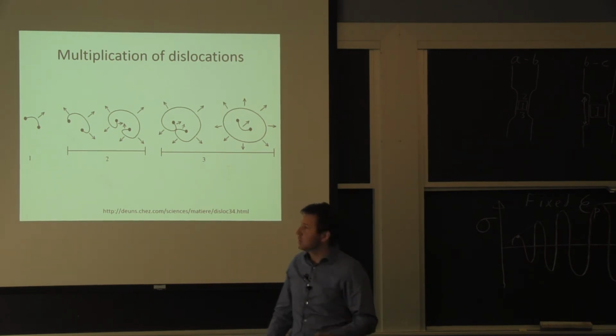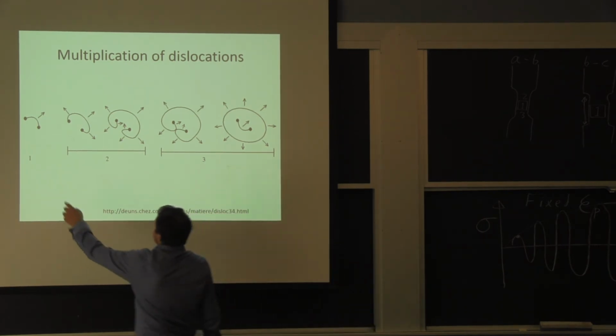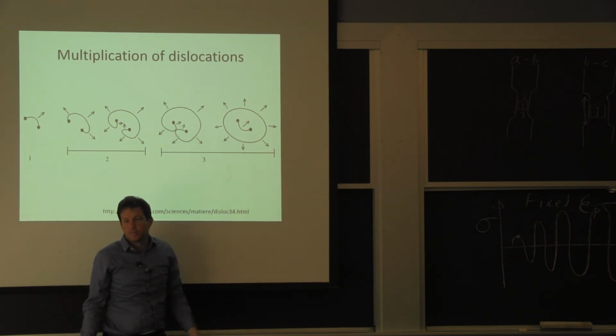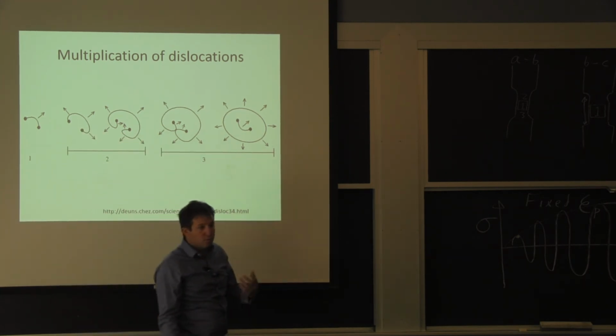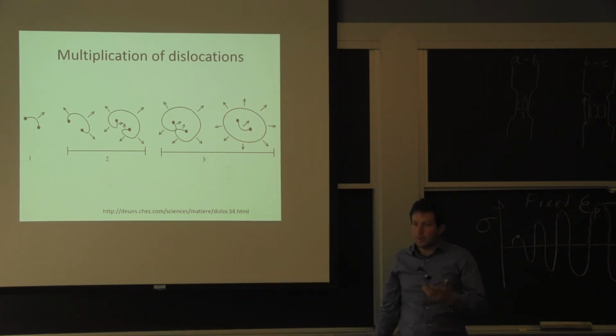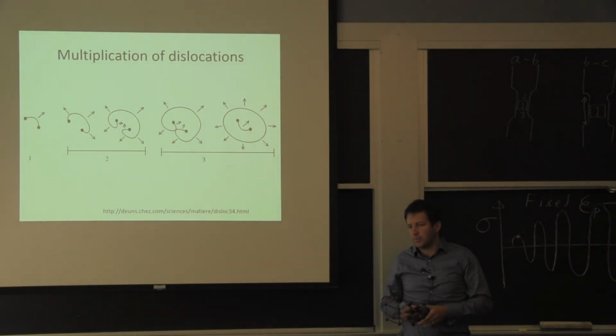The higher the temperature, the easier it is for the dislocation to keep jumping and moving around. At ambient temperature, you really need a force. But if you heat it up, it could start doing it on its own just based on the little residual stresses in that grain.